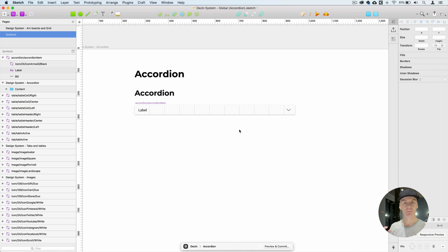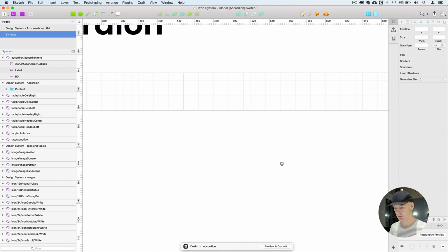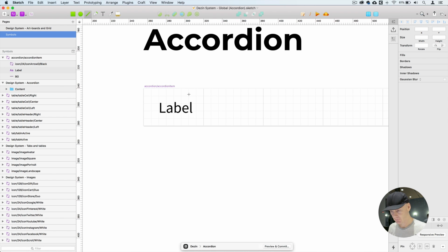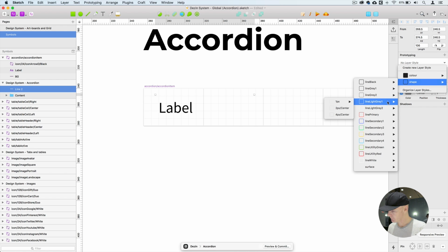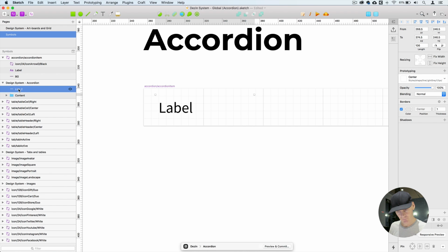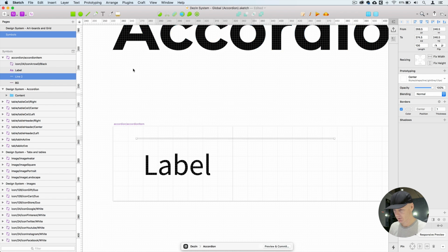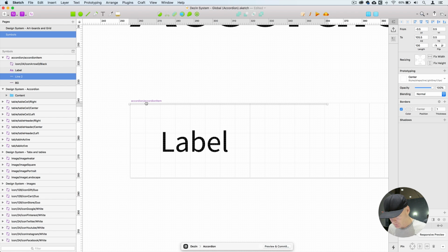With that done, we need a border at the top and bottom that we can turn off and on when we want. So we're going to have to make a symbol of a line. Let's grab the line tool, just click and drag it out, change it to shape, line light gray 1 pixel, center. Okay, let's make sure it's moved to where it should be on top of the background layer. Let's move it into place. Make sure it's 688 wide.